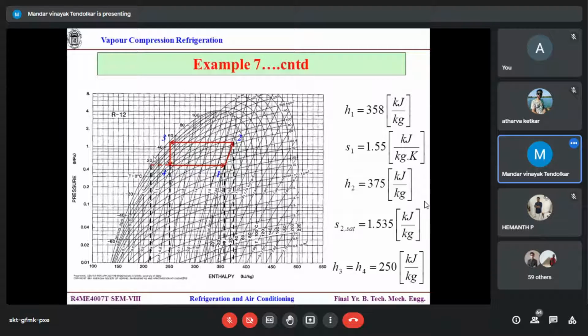And over here, draw a vertical line for 20 and a vertical line for 100. What you want is 15, so one-fourth of that total length from the 20 side. Draw the vertical line wherever it cuts, then draw the horizontal line. That is your 15 degrees Celsius line. Then find the intersection. If it falls directly on any of the isentropic lines, then you are fortunate. If not, use the same ratio, and here you simply draw a vertical line. That is done. Job is done.